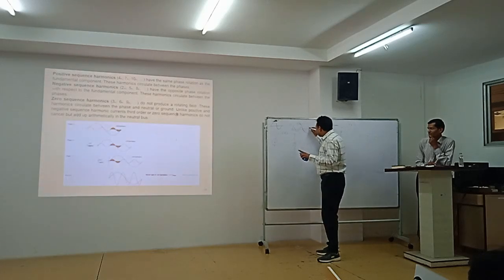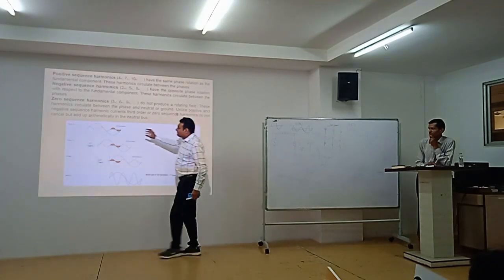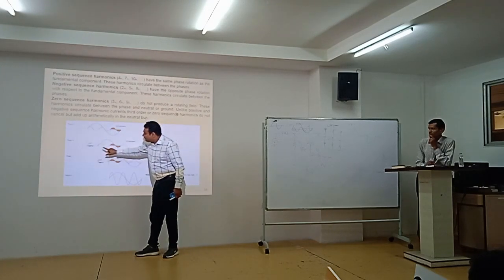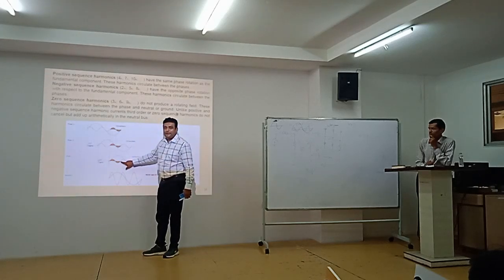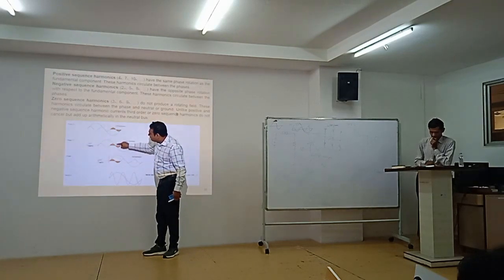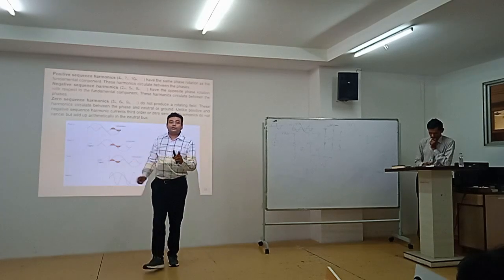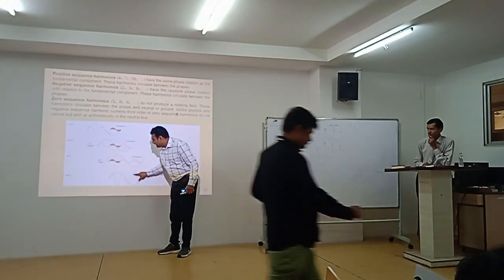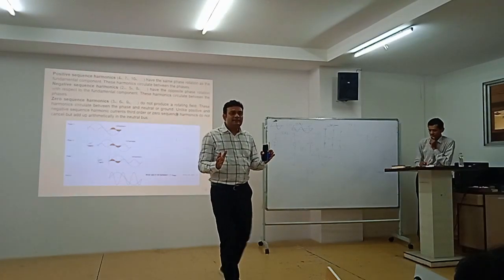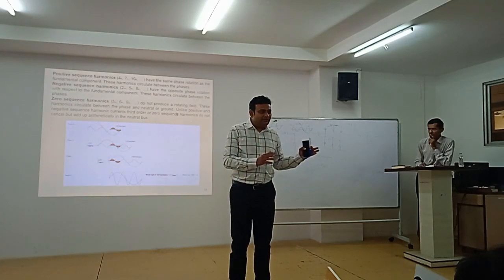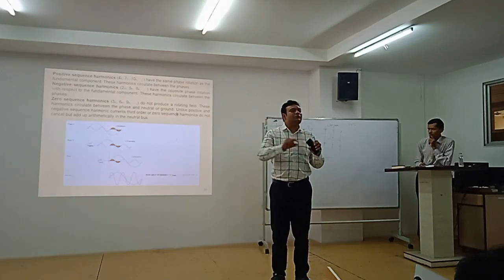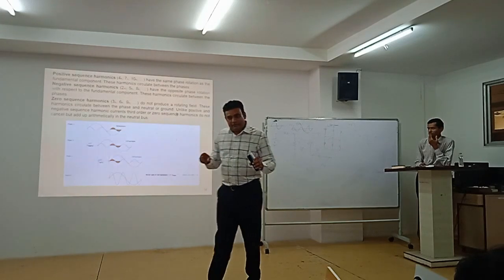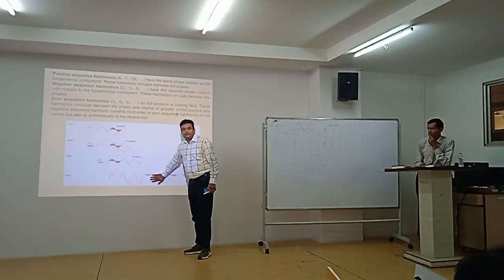Cycle, second cycle and third cycle, right? So you can see here phase A third harmonic third cycle, phase B third harmonic second cycle, phase C third harmonic first cycle. So at one particular point, this all will come in a single point. So if your neutral system is available, all three become additive and neutral current harmonics will become higher. Normally neutral wire we design at half size. So if a third harmonic of 3 ampere, and say 8 ampere neutral is designed, all three phases R, Y, B become 9 ampere, and so it will give a fusing of the neutral wire.